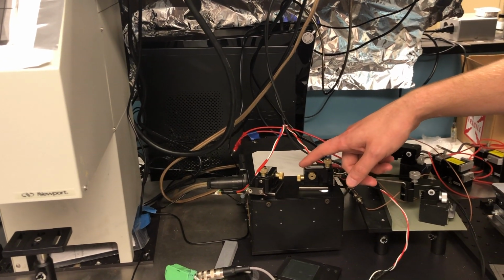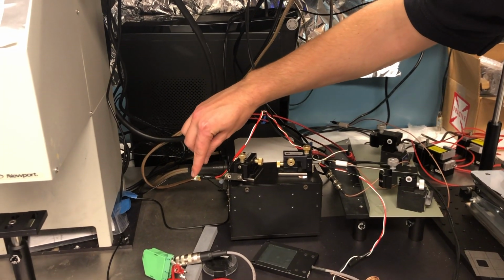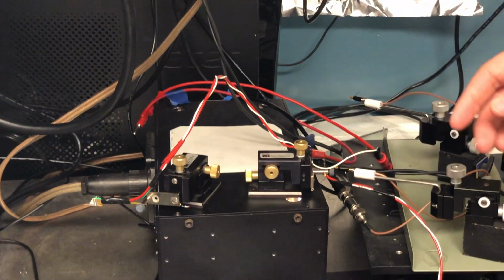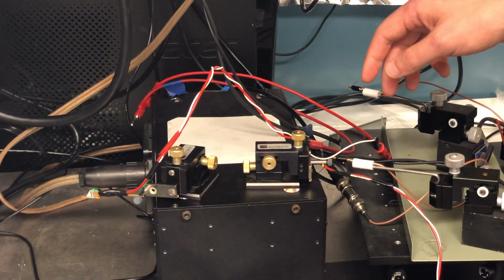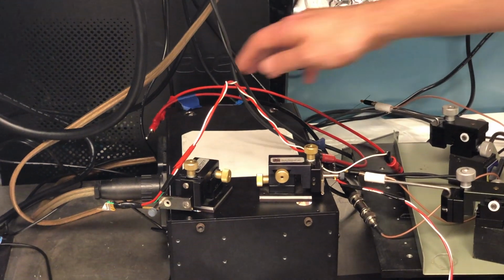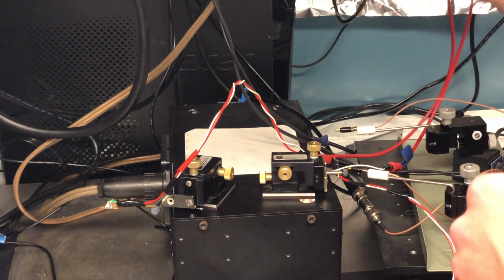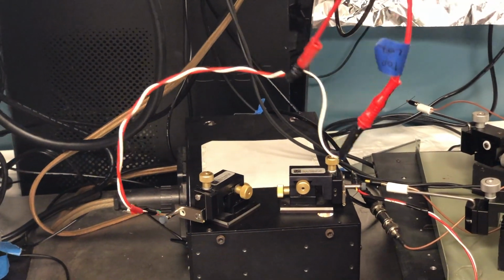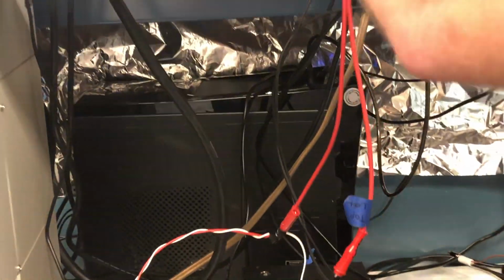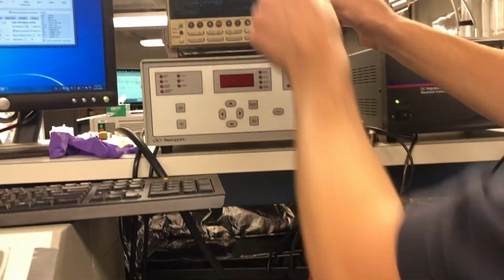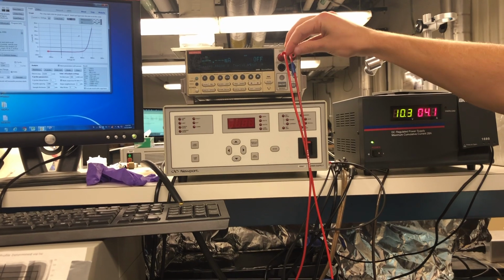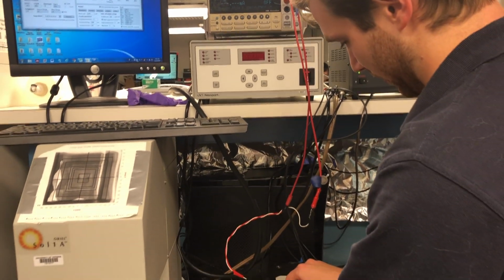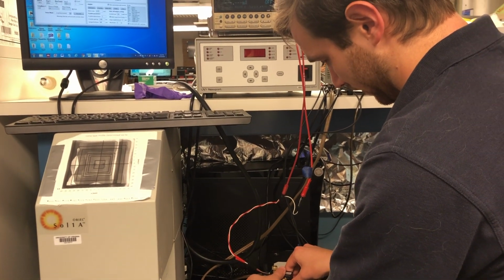We have a 4-point probe set up here. So each of these probes has two tiny little fingers on them, and that's to help reduce some of that lead resistance that we're going to encounter. And you'll notice each probe has two wires coming out. So for the one on the positive end, I'll put the positive end on both the two positive ones. Again, they're in the same place, but we're going to set it up for the 4-wire sense method. Then I can place my probe on the center terminal.